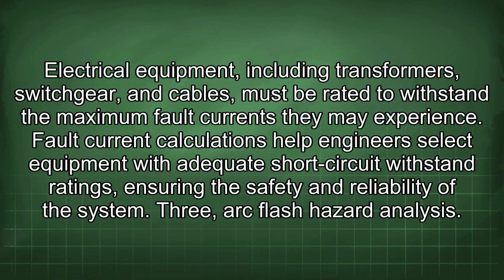Electrical equipment, including transformers, switchgear, and cables, must be rated to withstand the maximum fault currents they may experience. Fault current calculations help engineers select equipment with adequate short-circuit withstand ratings, ensuring the safety and reliability of the system. 3. Arc flash hazard analysis.